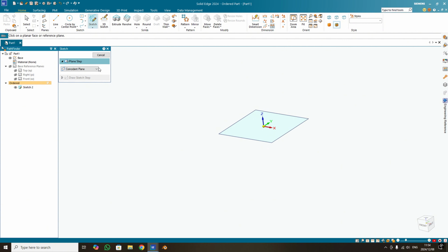So our next plane that we can select will be a parallel plane. This is useful when you have to create geometry for 3D lots and those types of things. So Solid Edge will ask you to select the plane that you reference from, which would usually be either a plane on the coordinate system or a face on a 3D model that you may already have.